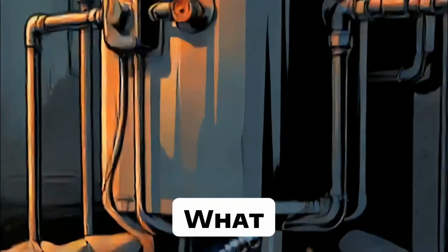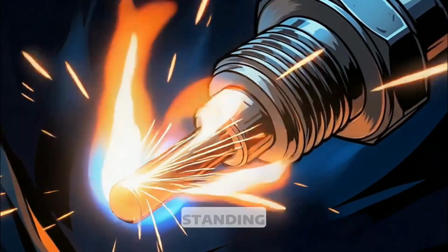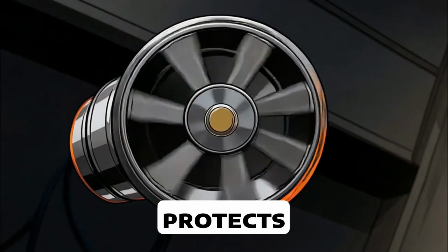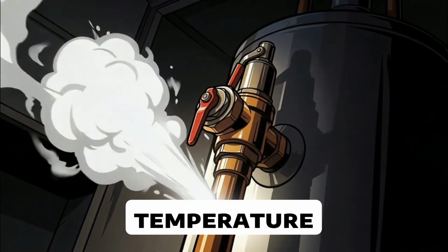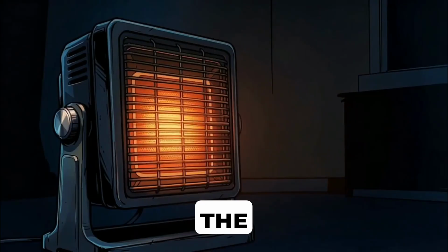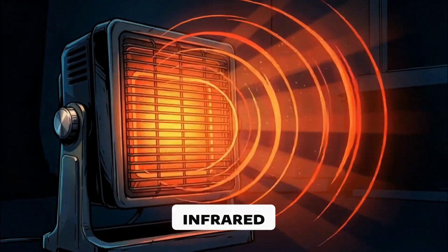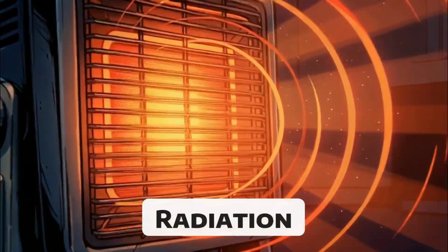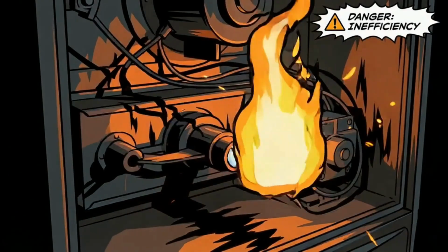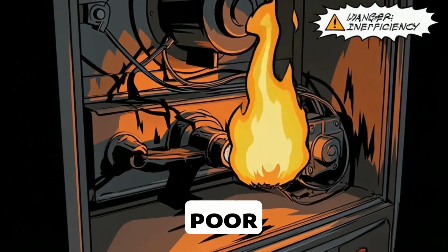Boiler. What proves pilot flame on many standing pilot systems? Thermocouple. What protects a water heater from excessive temperature and pressure? T and P valve. What is the main heat transfer method of an infrared heater? Radiation. What does a yellow flame usually mean? Incomplete combustion or poor air supply.